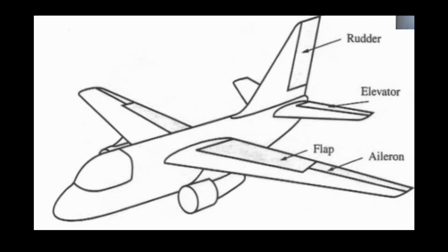Additionally, sometimes a pilot will be required to use multiple control surfaces at once. For example, when turning an aircraft, a pilot not only deflects the rudder, but also deflects the ailerons in order to bank into the turn rather than turning sharply. While this may seem complex at first, it is easy to understand with practice. You can do this at home by building paper airplanes and attempting to control the direction in which they fly.